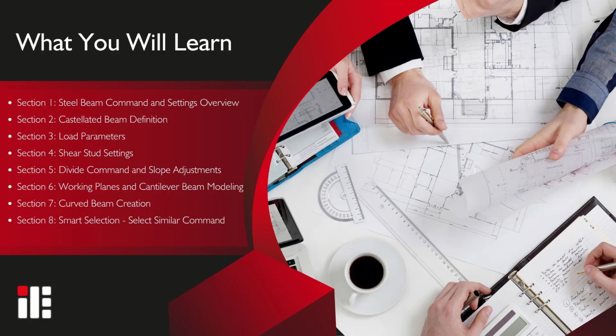In this video, we'll explore the steel beam command and how to place and configure beams in ideCAD Structural. You'll learn how to define beam properties, including section, material, elevation, and alignment options. We'll also show you how to create castellated beams and apply shear stud settings. You'll discover how to assign load parameters and use the divide command to split beams or adjust slopes.